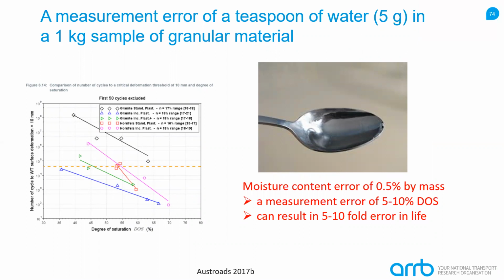Thanks for the presentation. It has been shown that the mechanical behavior for both subgrade and granular material is highly dependent on moisture. For subgrade soil, the moisture content affects the suction and thus changes the suction stress of the subgrade. For fine grain soil, suction level can be very significant.